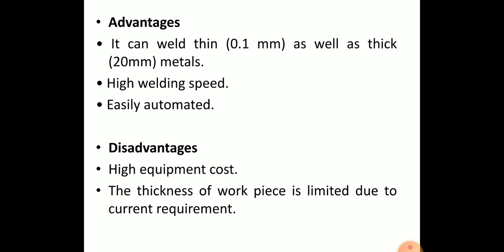Then the applications of resistance welding: joining sheet bars and tubes, making metal furniture, making fuel tanks of cars, tractors, etc., making containers, welding aircraft and automobile parts. This is the application of resistance welding.